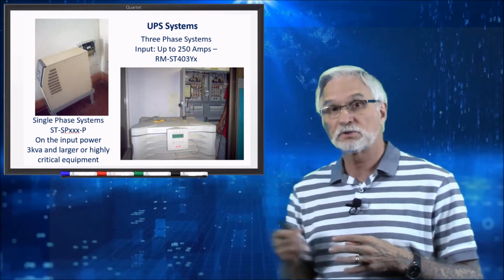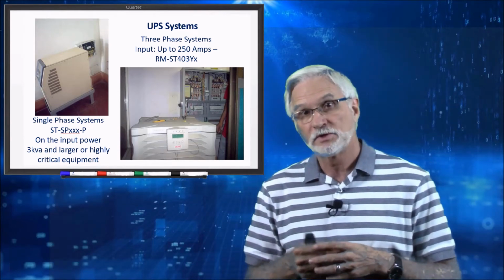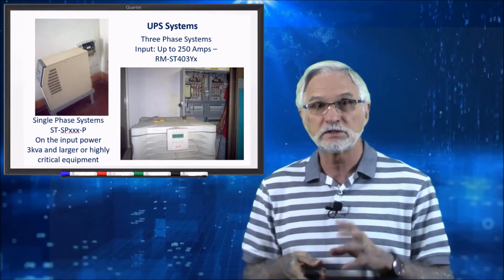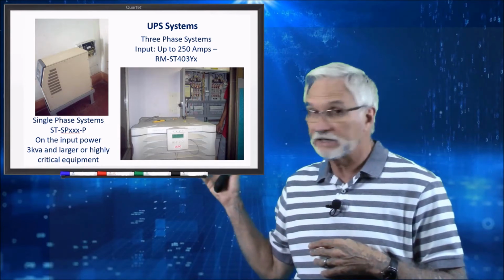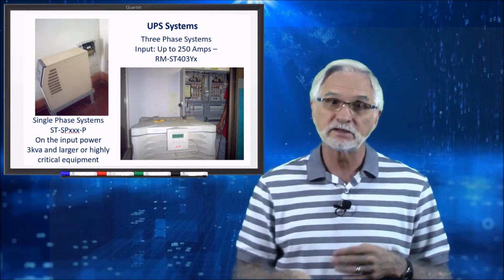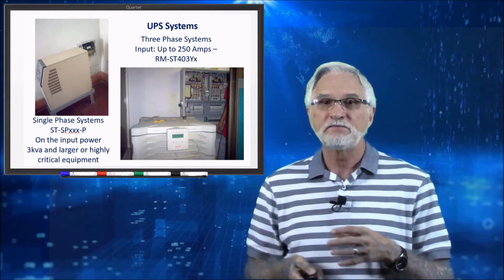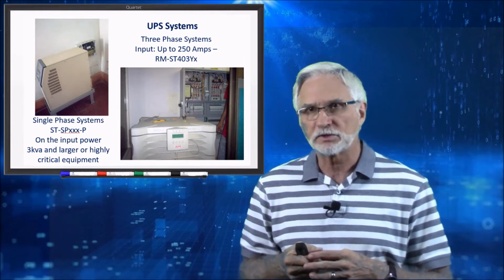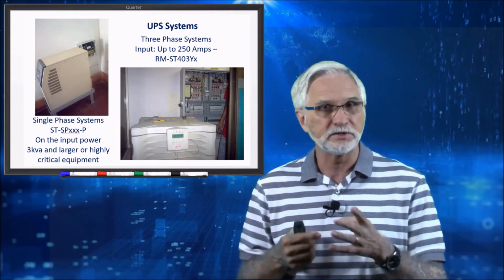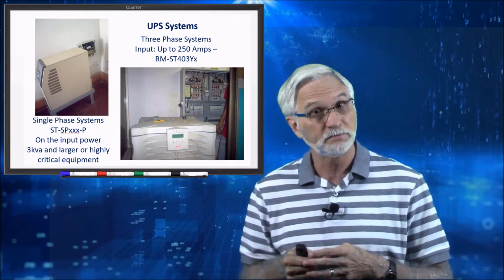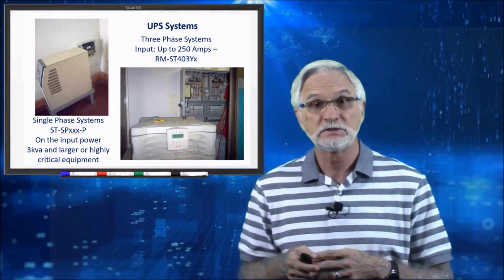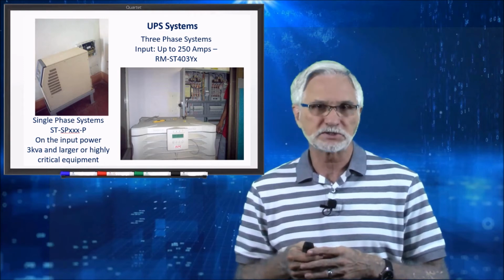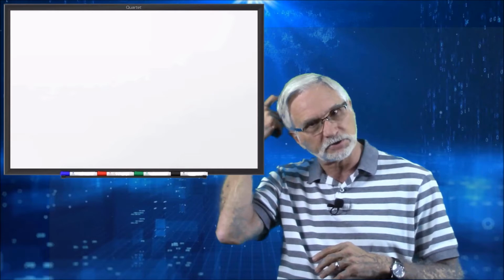Now, also on some of our other photos here, you can see where we've done installations. The back is towards the input. Main panels on the larger units. In fact, we can go up to, I think in our nomenclature, a 300 kVA unit, and then we're looking at maybe an RMST 120, depending on the voltage. But typically you wouldn't need to go much higher than that, because that's about 800 amps, and that'll absolutely protect everything you need to protect. So that's about the maximum on that.